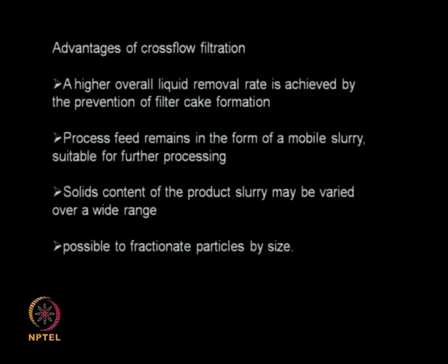So the advantages, as I said, are that the removal rate is very good and it prevents cake formation, and the feed remains a mobile slurry, unlike a normal filtration where you have the solids and the slurry sitting on the solids. We can look at different percentages of solids present in the slurry, and it can also do fractionation of the particles by size. That means I can get solids of different sizes separated using this approach.